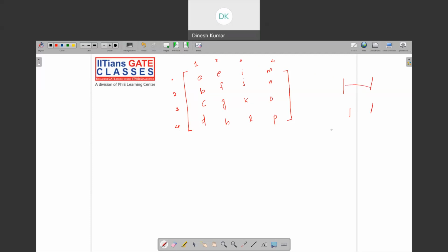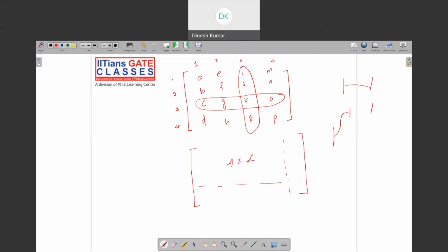Now we are continuing with a 5th bus, which is connected to our 3rd bus. So we have to take the 3rd row and 3rd column. Now you have to create a new matrix, so now it will be 5 by 5. So you have to keep this 4 by 4 matrix similar here. Just keep this here, 4 by 4.